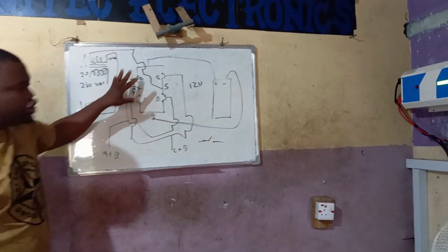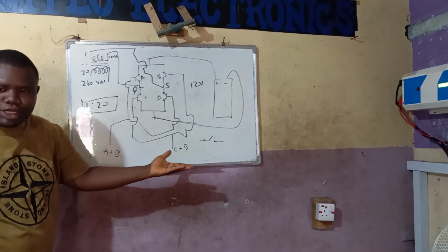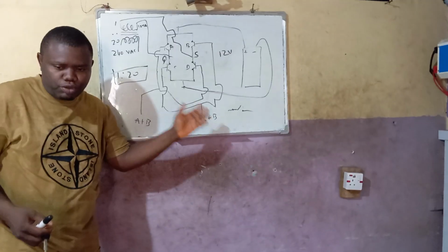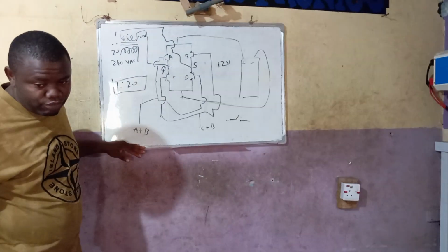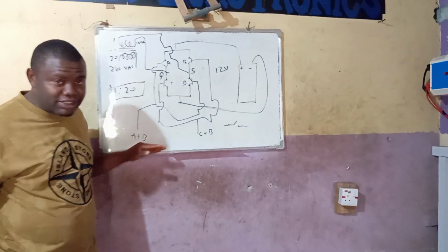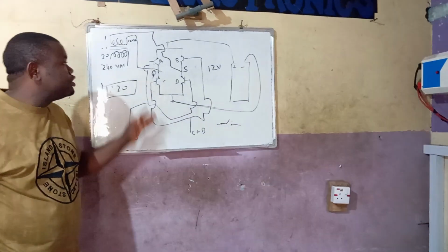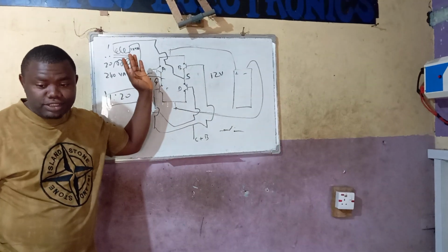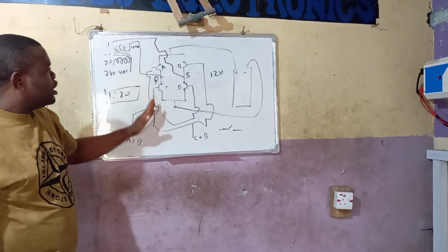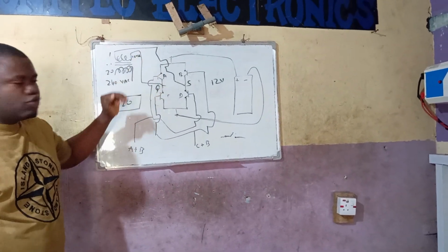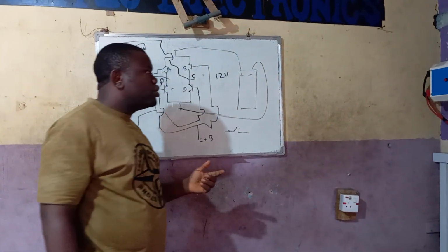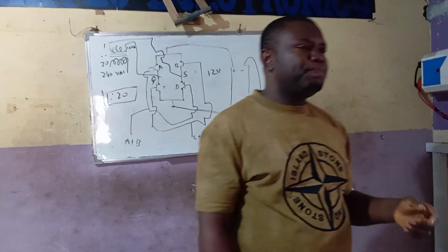Yes. And so the polarity is in one direction, that is plus or minus. If this one is off, because this one has to be off. If it doesn't turn off, and the 2 of them are on at the same time, it's a problem. It simply means you are turning on all the 4 transistors at the same time. That means you are bridging the system. You get the point now. So this is the basic explanation of the H-bridge.